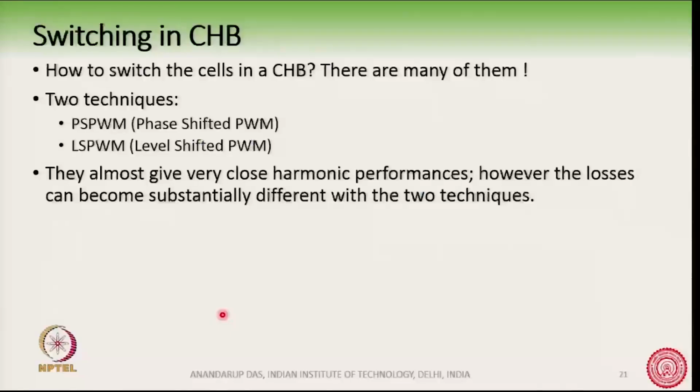So, the performance with phase shift PWM and level shift PWM is almost the same in terms of harmonic performance, although LS PWM is slightly better. But the losses, if you use these 2 PWM techniques, can become substantially different with the two techniques. In fact, for level shift PWM, the loss distribution will get highly unequal or uneven, and there are techniques again to counter or to rectify this uneven loss distribution.